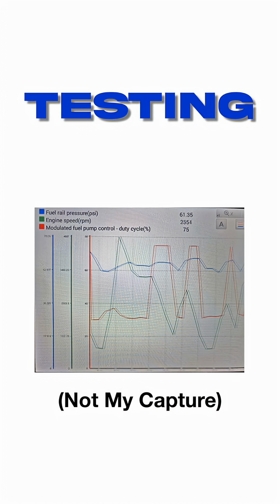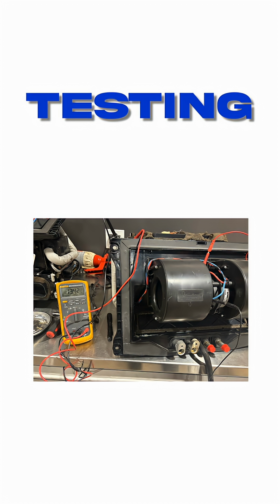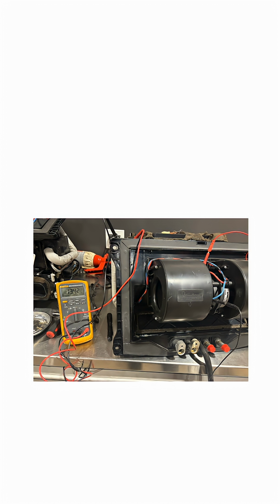When diagnosing PWM circuits, we're mainly trying to confirm three things. Firstly, that the control module is outputting the correct duty cycle, that the signal is reaching the load, and lastly that the load is responding relative to the duty cycle. For example, if you have a 90% duty cycle out of a fan, it should be almost full blast. And if you have 10% duty cycle out of a fan, it should be barely on.